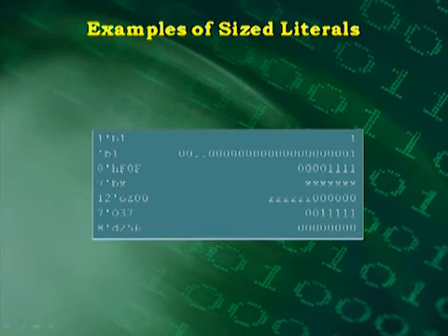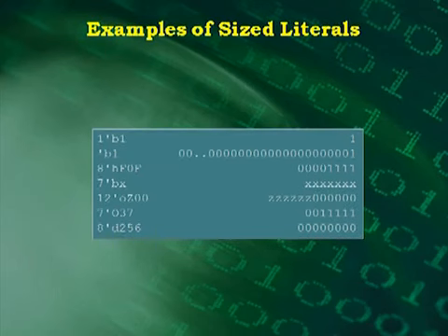Somebody asked if 32 bits is an absolute limit. No, it's not. We're going to talk about that. That's just the default. That was pretty much the standard in Verilog 95, but no, you can go much wider. In fact, in one design I did not long ago, a DDR2 DRAM controller, my internal bus was 432 bits wide. So hopefully that answers it.